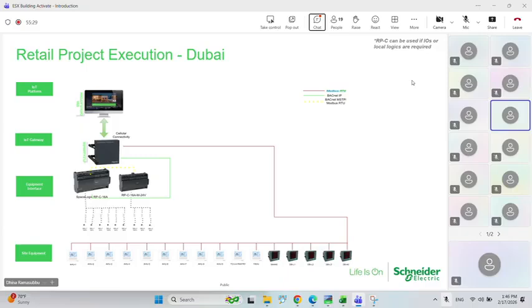We found a suitable Schneider replacement thermostat, a communicable one, the TC903. They have dedicated DBs for lighting and AC, so we put energy meters on all those DBs. The reason was that this helps us identify the loads, so that with a pre-control and post-control period, we can prove the energy savings and how much we achieved.